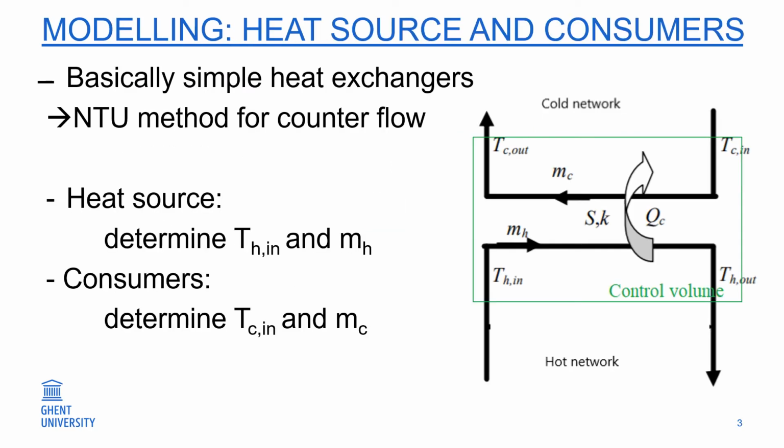The first two components that we'll discuss are the heat source and the consumers, because they are actually pretty similar. They can basically be modeled as simple heat exchangers. We have implemented them by using the NTU method for heat exchangers of the counterflow type. We don't have enough time to go into the details of this method, but it's exactly the same as we have seen in some other courses.